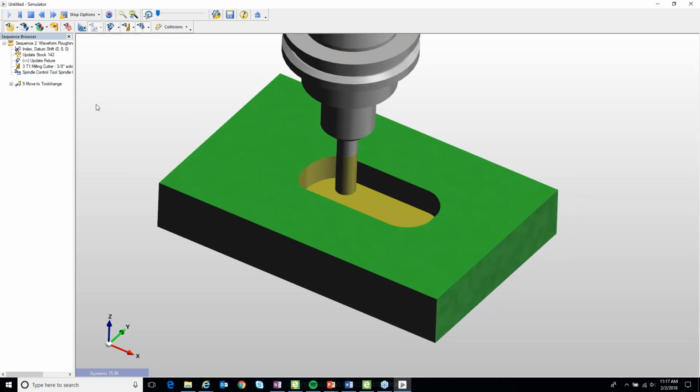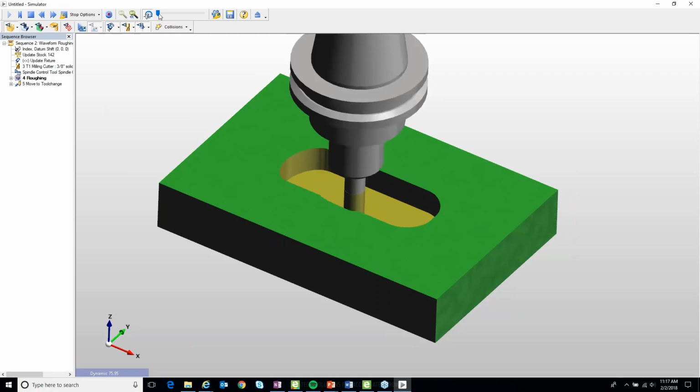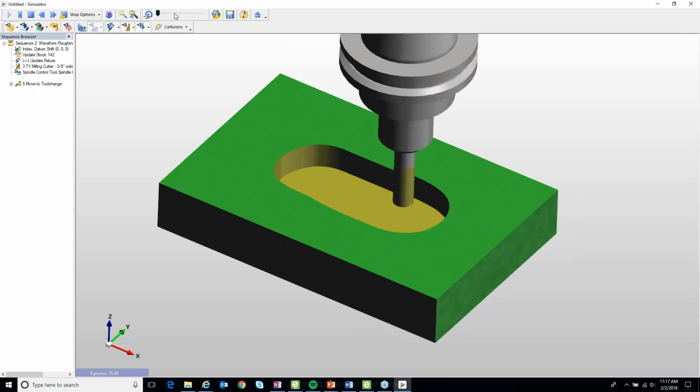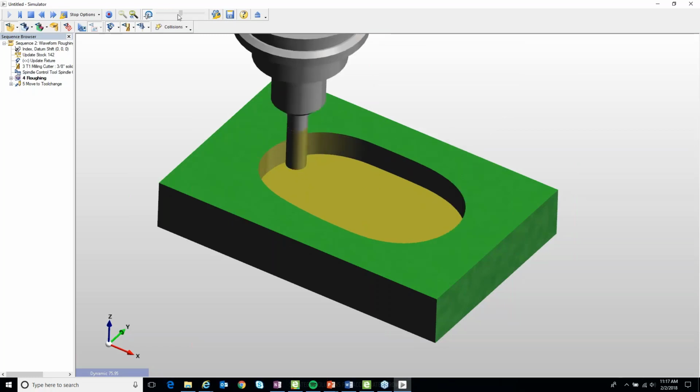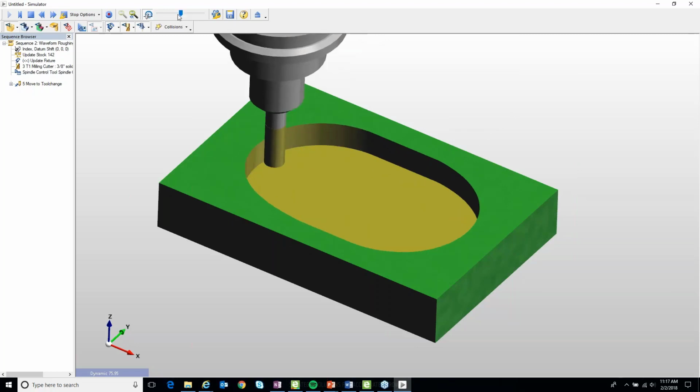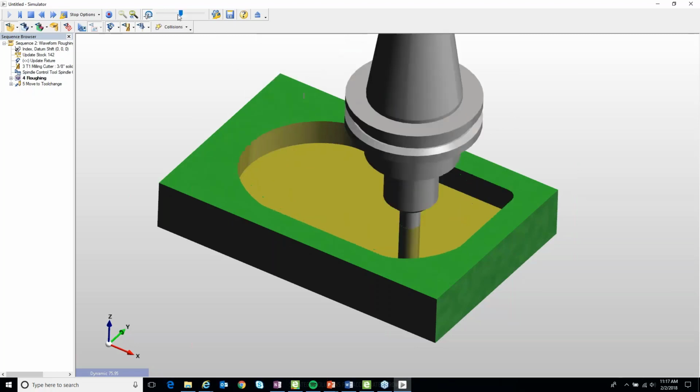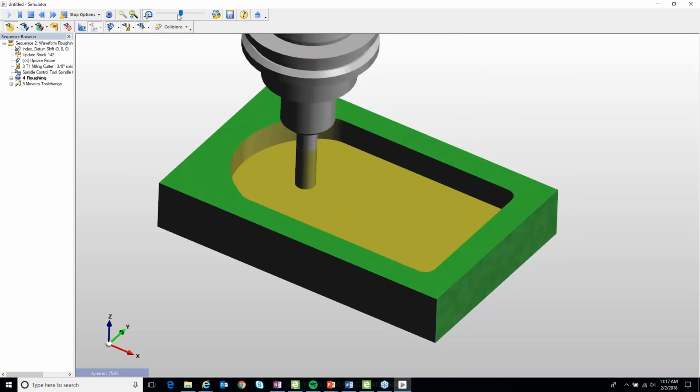But as the software begins to then open the shape up, I'll speed this up a little bit. You'll notice that as the tool heads into the corner areas, it stays in those corner areas to work them out completely before going into the next one. This is a much more efficient path. It eliminates the tool path fragmenting, a lot of the tool lift up, and other things that would be typical with a geometric collapse type shape.